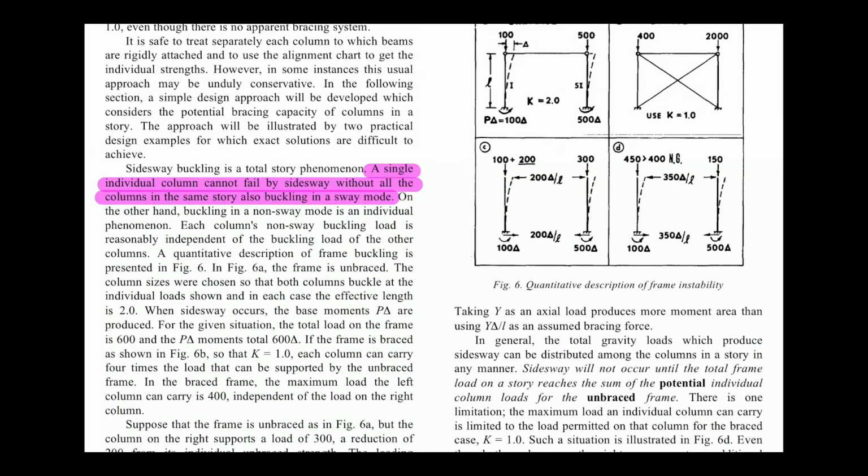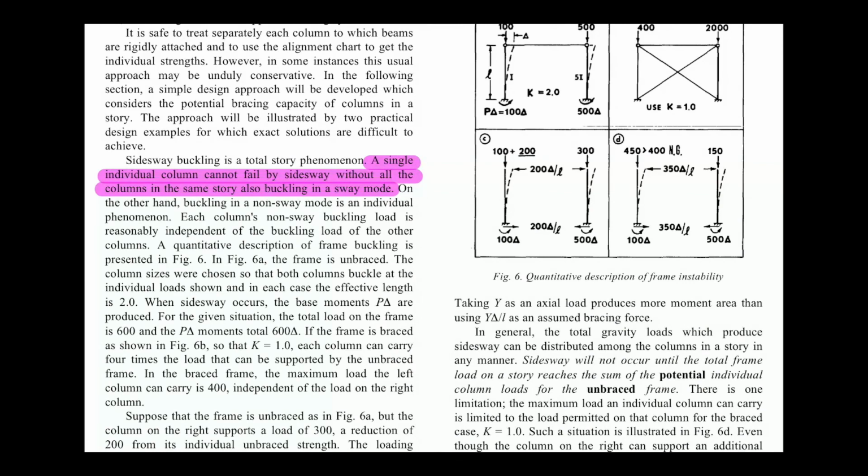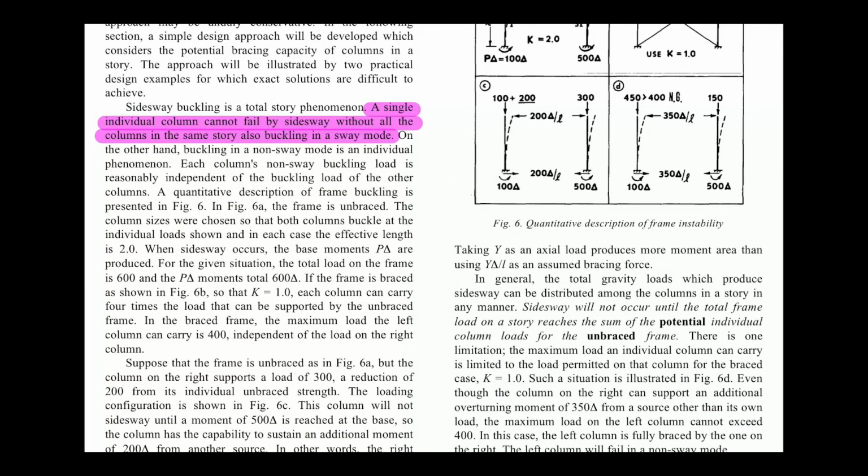This might be bothering you, I know. The 1.0, you see that this looks like a fixed support, sir. I don't have a good feeling about the 1.0. Okay, don't worry too much about this. When it forms the inelastic buckling fully, then the hinge could also occur, and this is just a matter of fact that the author just wants to illustrate the problem for you, so he just goes with the simple K for the case of the unbraced frame illustration.